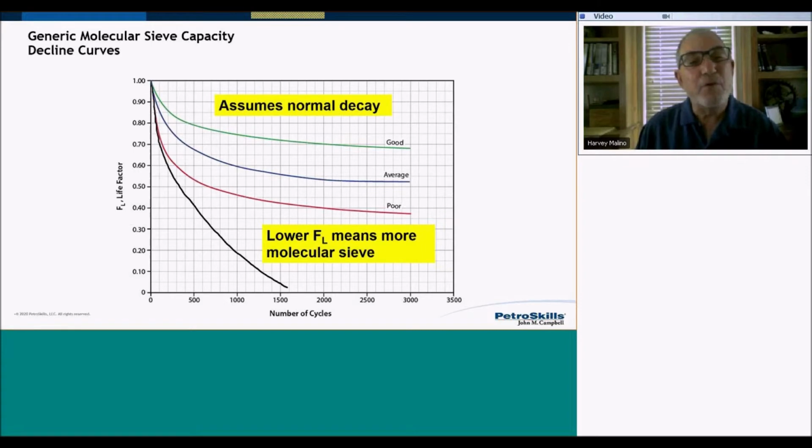You remember before, when we looked at the isotherms, we said you had an equilibrium capacity of 23.5 weight percent. And then we modified that by adding a residual loading, and that reduced to 19.5 weight percent. That is only applicable to the equilibrium section.